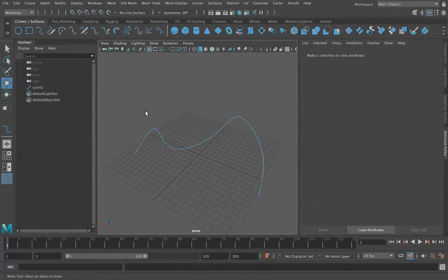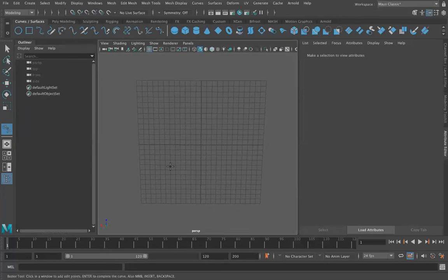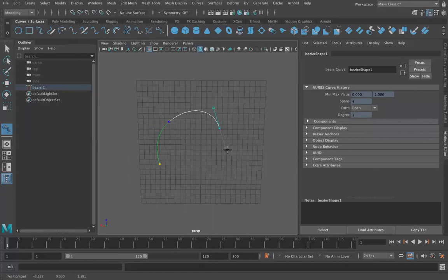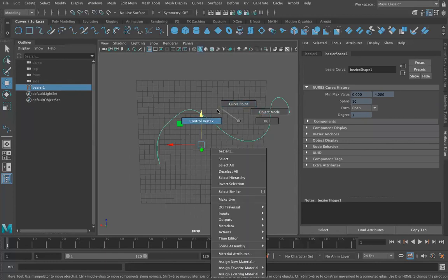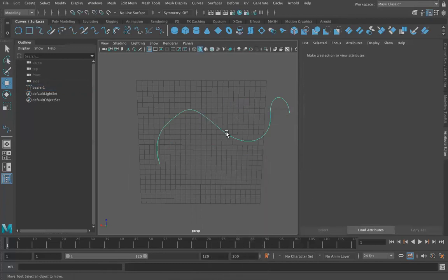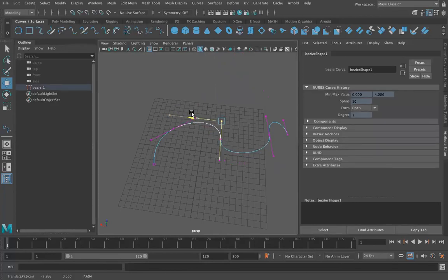There are a couple other ways to generate curves. That's an EP curve. There are also arcs, and then there are some curve editing tools here. But this very last one, which you might recognize from Illustrator if you've used Bezier curves, is maybe more intuitive for those of you who work with Illustrator, but you're going to be creating Bezier curves using those curve handles. But we don't have edit points here now. Instead I still have control vertex points, and these control vertex points are now those Bezier handles.